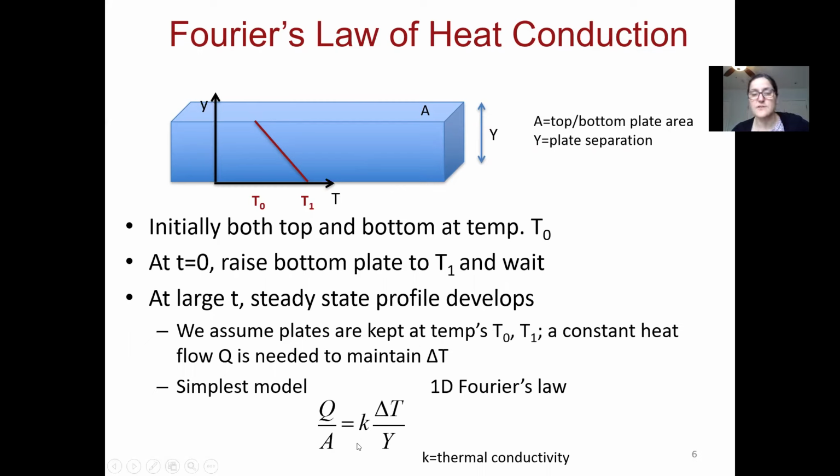The coefficient of proportionality is thermal conductivity K. This is going to be T1 minus T0, and since I'm always flowing from higher to lower, and every coordinate system points from lower to higher, we have to have that traditional minus in these relationships.